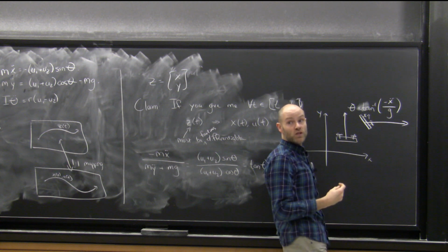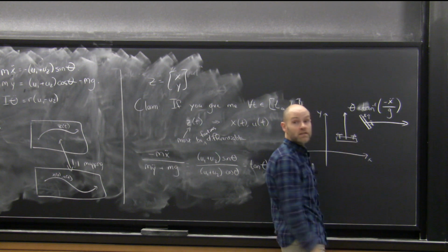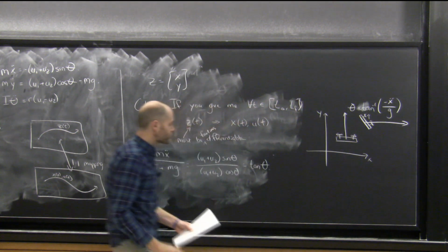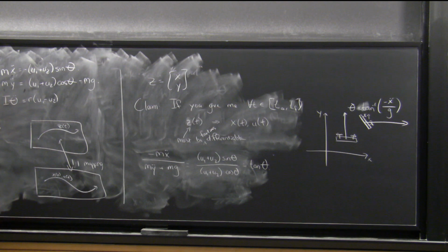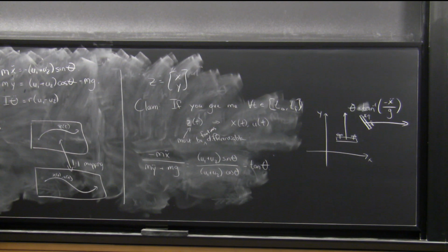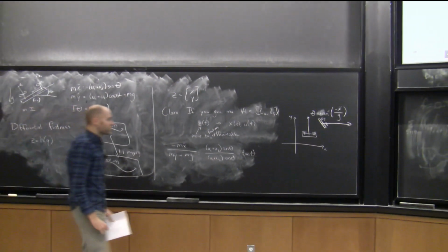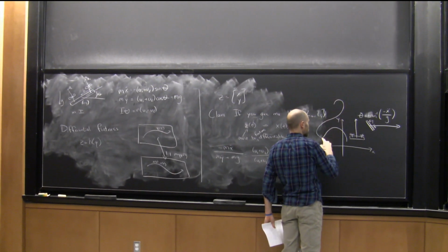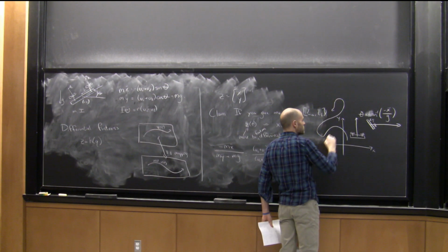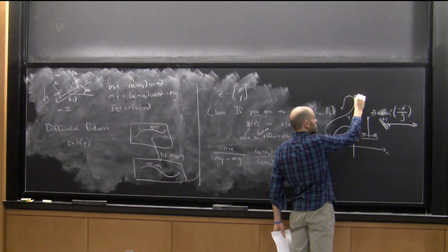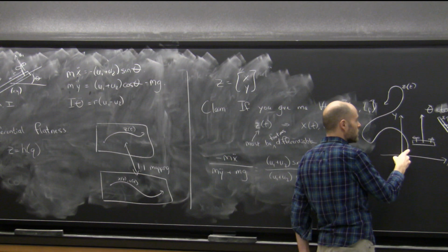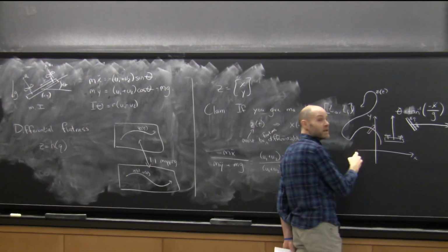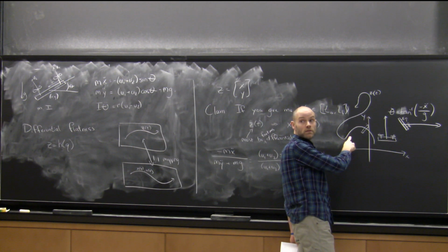There's a unique solution to that, which is some angle like this, and that comes right out. So if you were to draw any smooth trajectory here in this z of t, with no kink, then there's a unique solution to what my quadrotor has to be doing based on the accelerations of that curve.